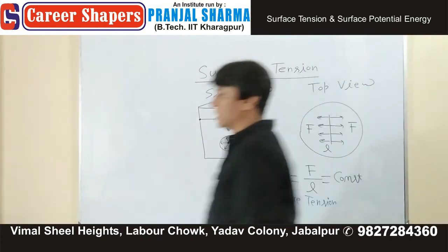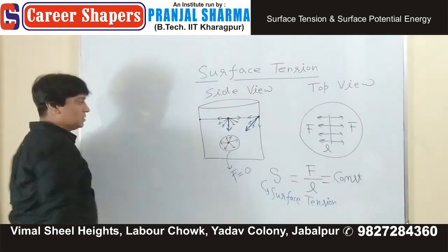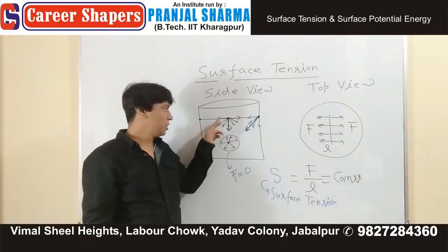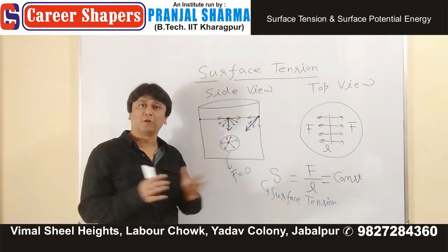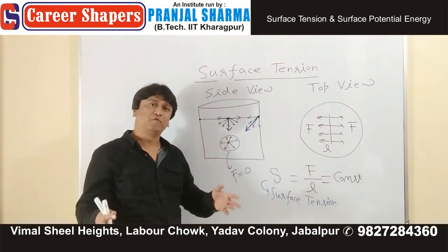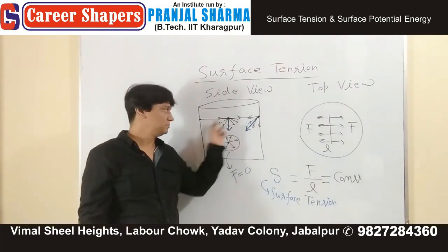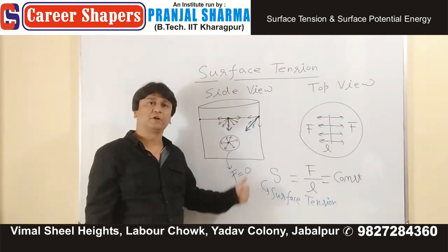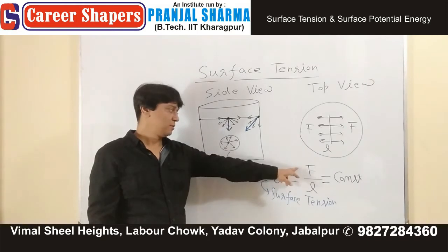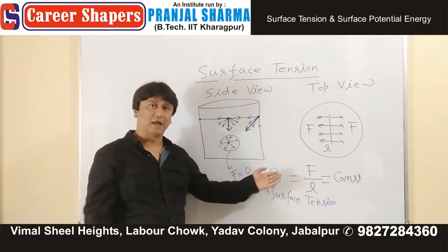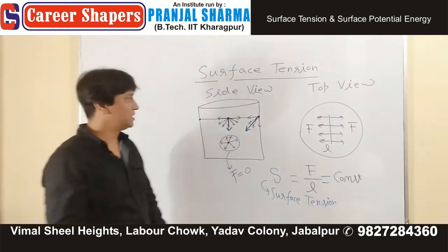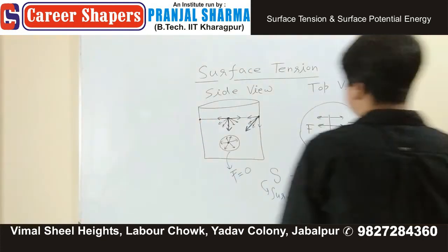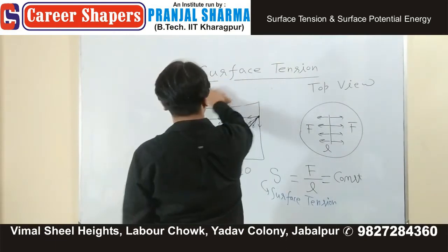Good. It should decrease, because if you increase the temperature, these molecules' separation first of all will increase, and as separation increases, that force part will also decrease, and therefore surface tension, force per unit length, is also going to decrease. Mention this. As temperature is increased, surface tension decreases.